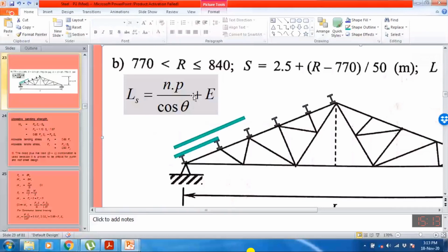So for example, that option may be this one. It means that that is a 4 meter length, so there will be some gap left. So actually, we do not provide the end lap in between. So it means that to cover this, we need to provide the purlin at the center. That is not a good option because we always provide the end lap above the purlin. So just to fill up this gap, we need to provide a purlin also here. If the purlin is directly placed on this top truss member, that will be designed also as a beam. So we are not going for this option.